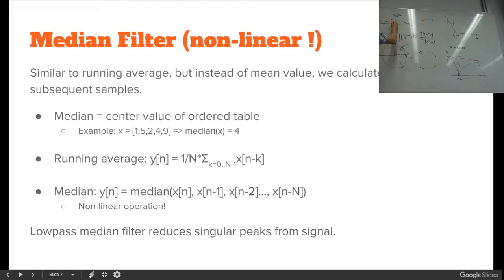So if we sometimes have an error on data. For example, you have a cheap sensor and you are reading it a little bit too fast, and then it gives you some funny results once in a while. How to get rid of those funny results? If you do linear filtering, basically a low pass filter, you will get a bump on each of those. But if you do median filtering, you practically remove these from data. Okay, is that correct, to remove real data? Yes, it is, if it works.